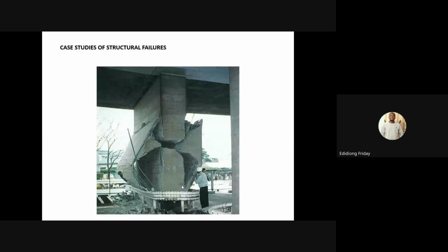Now, on this, I would like us to know that most times when structures fail due to compression, it is obviously because the compressive stress coming on the structural element is higher than the compressive strength of the structural element. And when you talk about reinforced concrete, you always hear that concrete usually takes care of compression, and the reinforcement takes care of the tension.